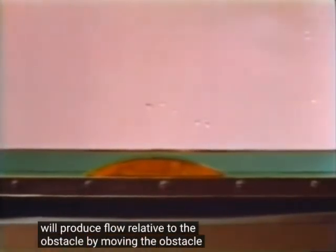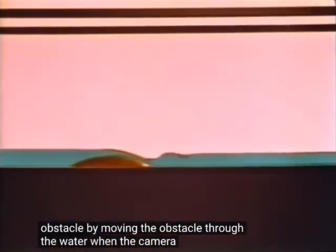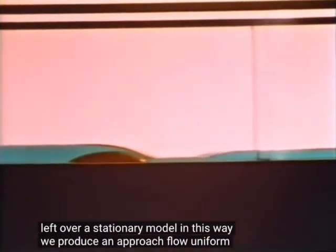We will produce flow relative to the obstacle by moving the obstacle through the water. When the camera moves with the model, we see an apparent flow from the left over a stationary model. In this way, we produce an approach flow uniform with height.